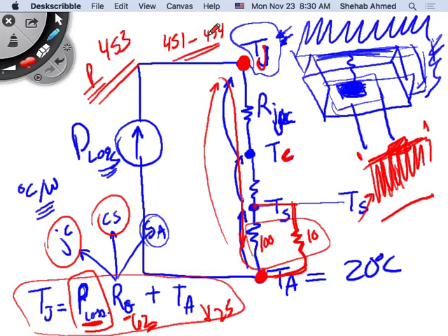If you want to optimize your device, your system even more, then fine. Dynamics are important. You want to see how fast the heatsink will help the device reach steady state, right? Because if the heatsink is very big, this is a thermal mass. The larger the heatsink, the larger the thermal mass that you are heating up, and they compare that to a capacitor, right? The larger the capacitor, the higher the amount of charge needed to raise the voltage of the capacitor. But then when you're at steady state, your voltage is steady, and you need just small charges, input and output, to maintain the voltage where it is, right? So same thing with the heatsink.